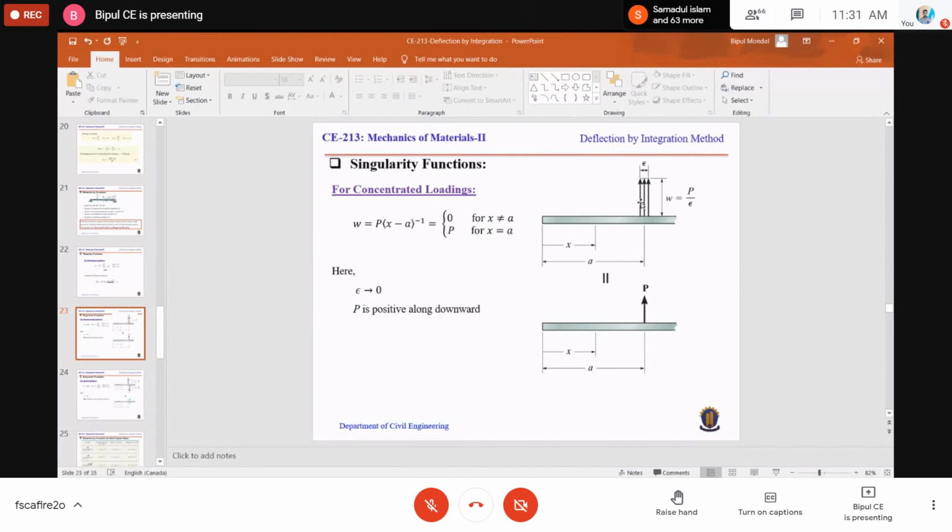Okay, that means there is no absolutely concentrated load, because the concentrated load must be distributed to the structure through an area. The size of the area may be small or may be big, but the force must be distributed through an area. And if the area is very small, then we can assume it is a point. But practically it is an area. It is not a point.